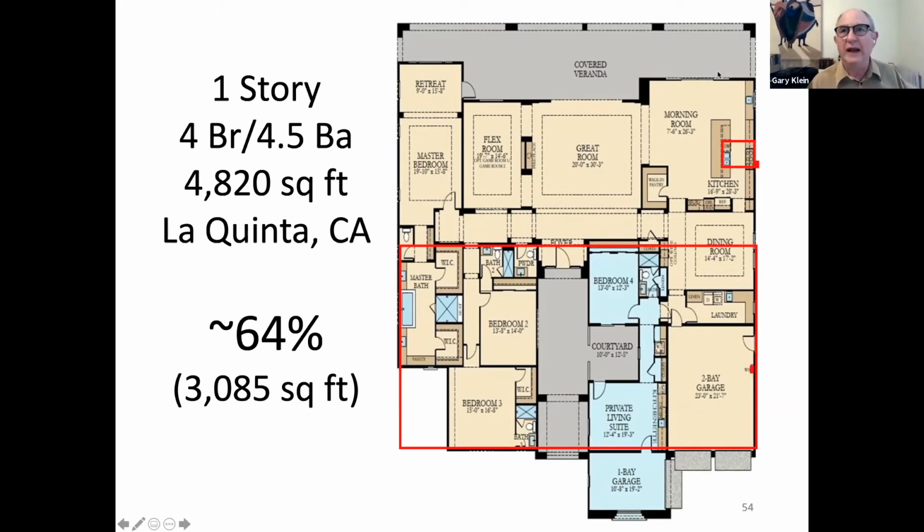So if we were able to do this today, I'd probably put the water heater under the counter here in the kitchen island, and I'd make it electric. Because of the time and year we did the project for the Energy Commission, electric water heating was not an acceptable option. So we had to pick gas water heating, and that could not go under that sink. So it had to be on the outside wall.